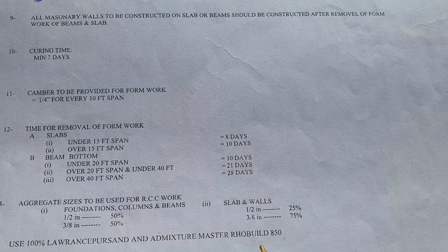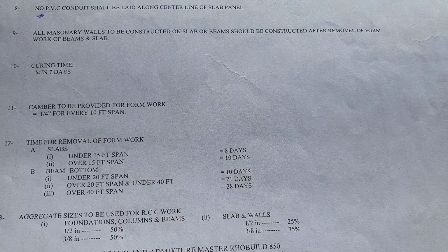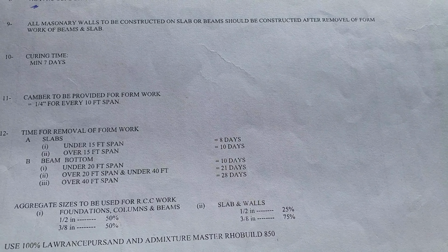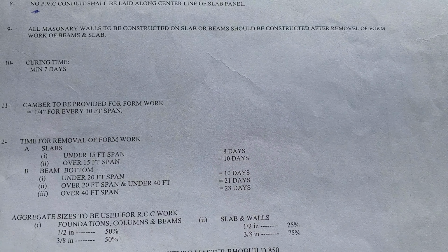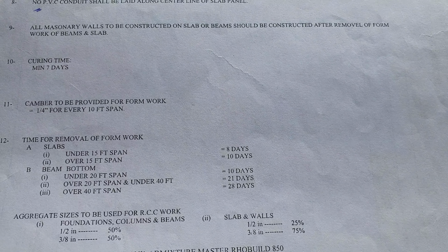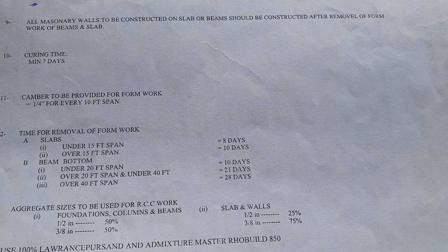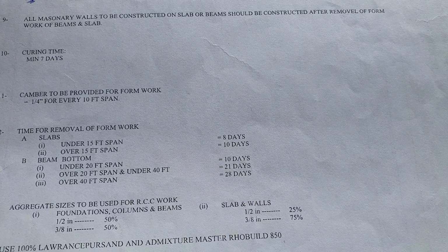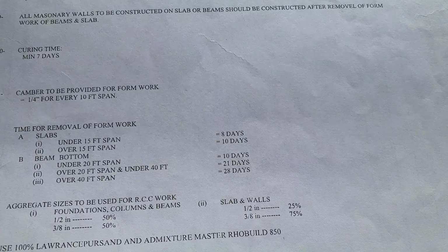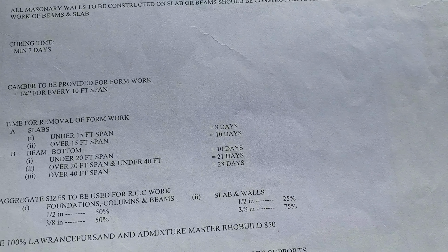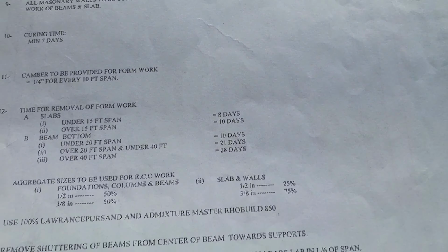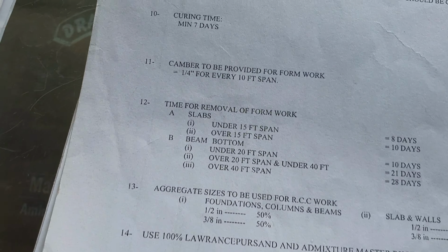For one cement bag we use 500 ml of this chemical for better settlement. If you do not use it as per requirement, or if you use more chemical, the strength of the structure will be reduced, because chances of segregation of concrete can happen.